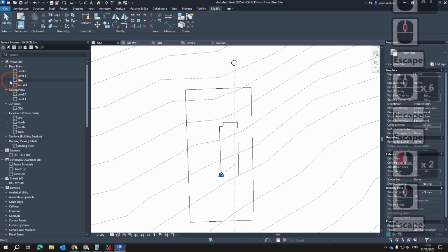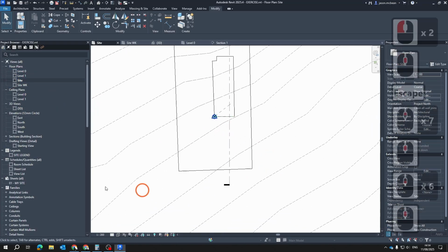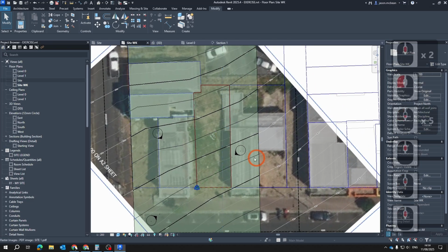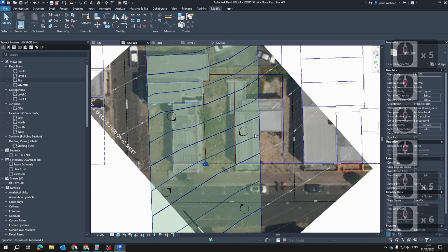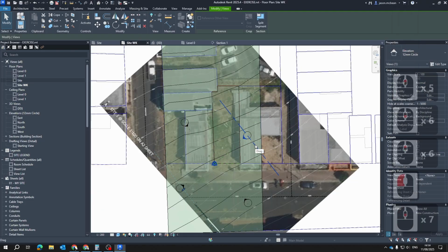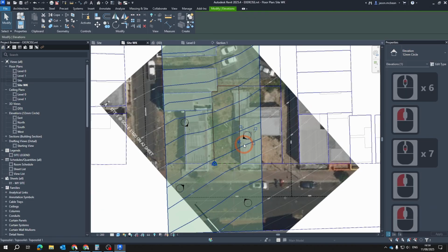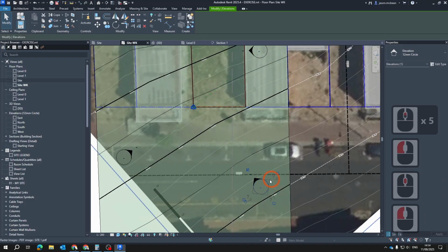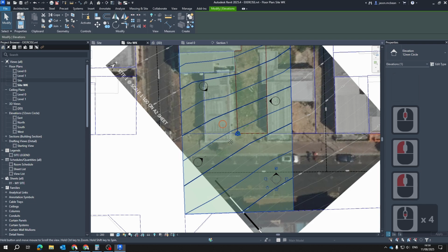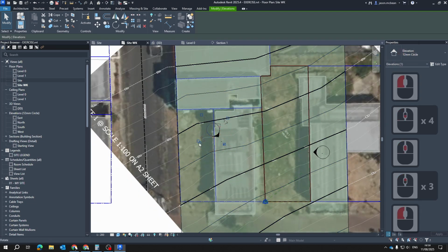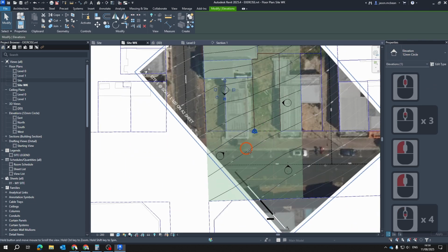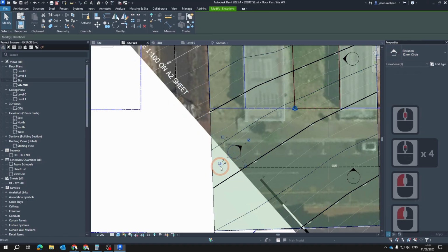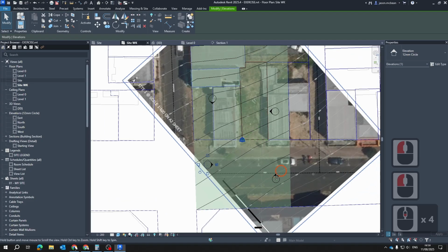Site, great. So back in the site view, now that we've got our project set up, we're not going to worry about the elevation markers for now, but they're very easy to readjust. You can select your elevation marker and you can rotate them, and you'll see it will start snapping square. Just remember that because we've set our project north, that's the reason why they're behaving like this, but we readjust them to be square with north, south, east, west.